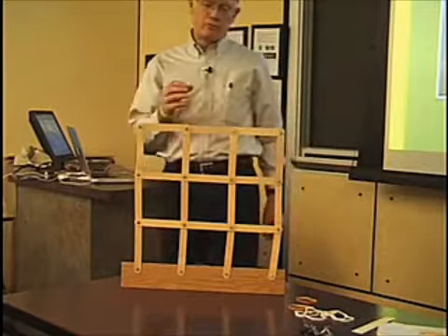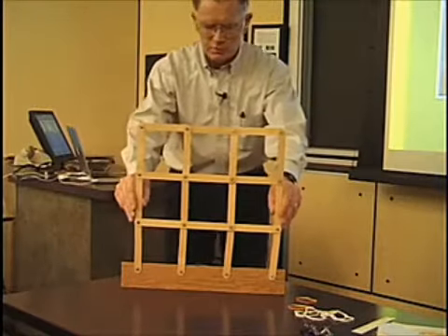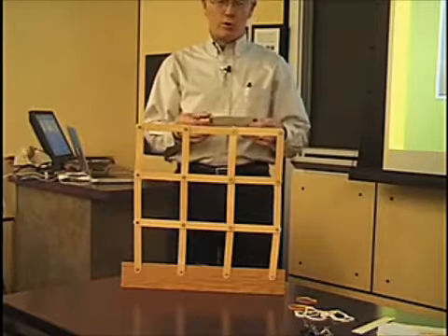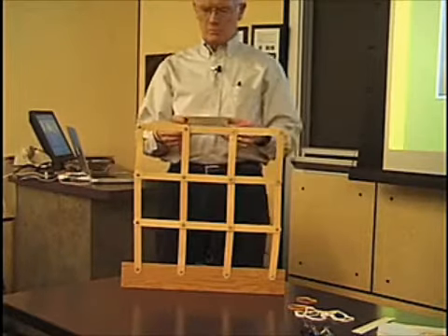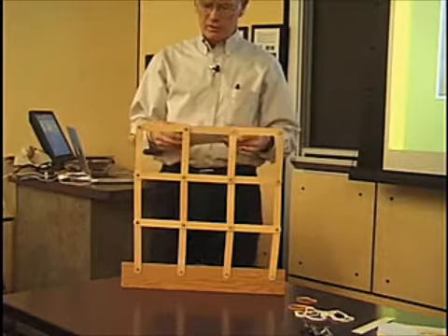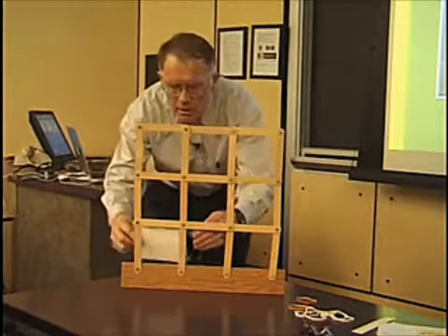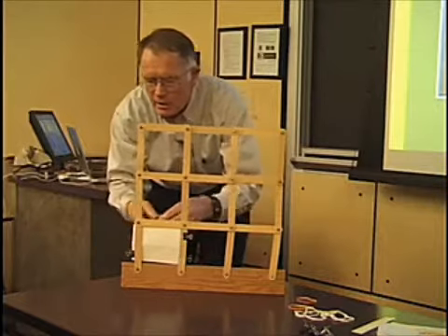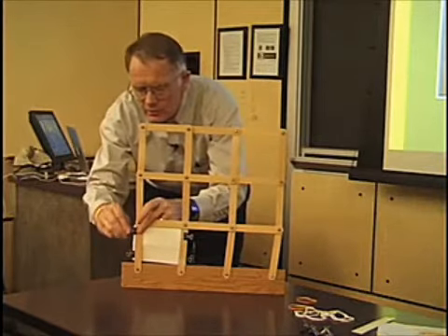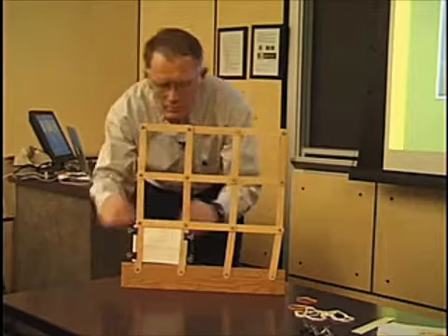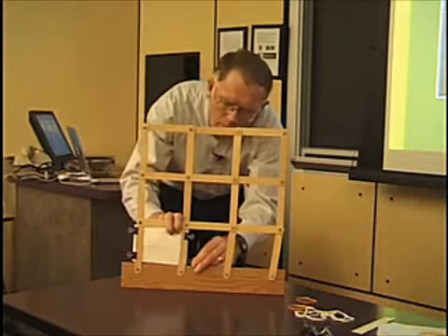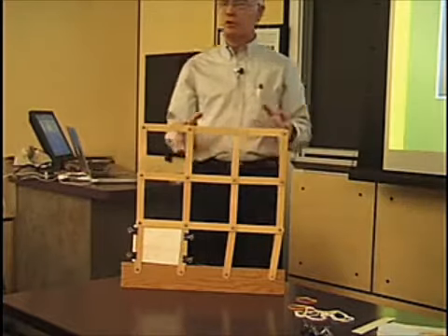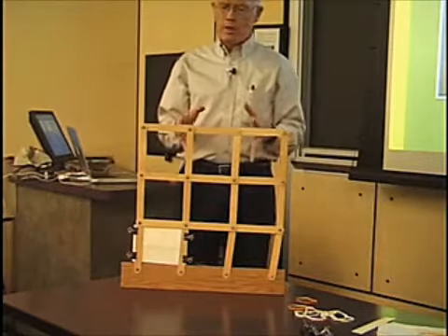Let's look at some options for how we can put shear resistance into buildings, put some shear strength into buildings. One way to do this is to put in what are referred to as shear walls. And so we can model that in this case with just an index card. So take the index card, fasten it on its corners to the tongue depressors. Now the index card is actually producing shear resistance, some shear strength in that bottom story.